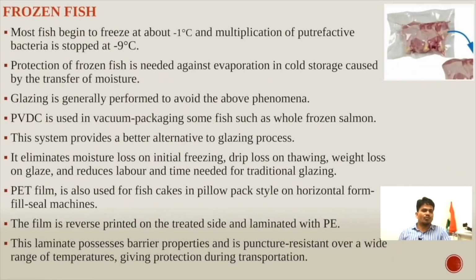Frozen fish. Most fish begin to freeze at about -1 degree Celsius, and the multiplication of putrefaction bacteria is stopped at -9 degrees Celsius. Protection of frozen fish is needed against evaporation in cold storage caused by the transfer of moisture. Glazing is generally performed to avoid this phenomenon.